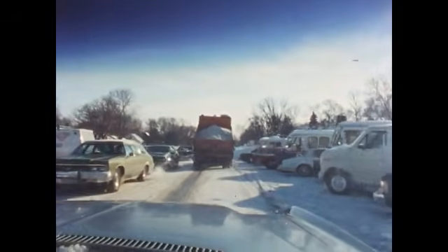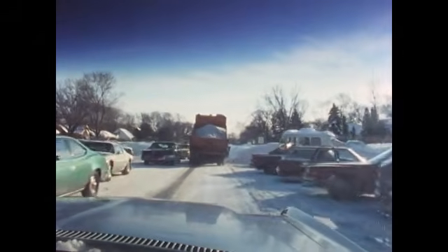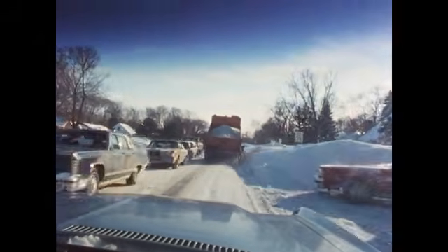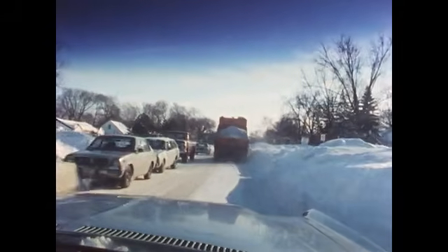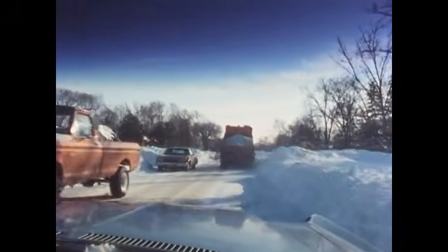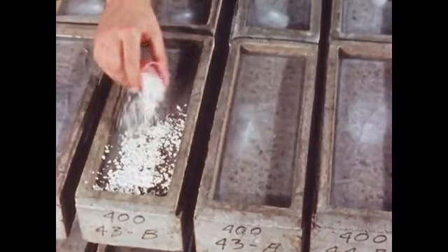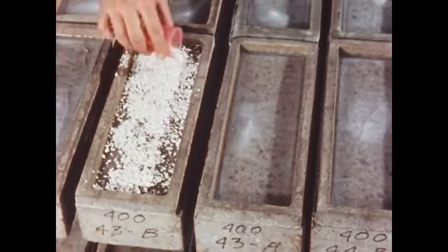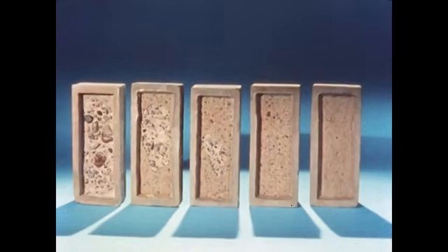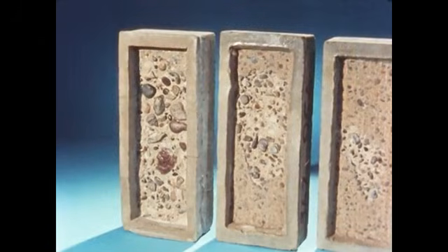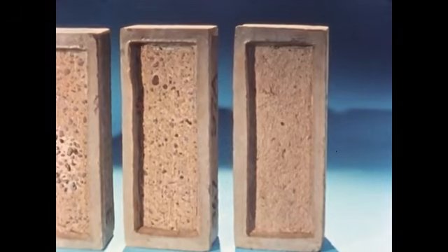Concrete pavements face some of the most severe exposure conditions: cycles of freezing and thawing, wetting and drying, plus the corrosive effects of heavy applications of de-icer chemicals. Each of these laboratory specimens, simulating pavement slabs, has been through 200 freeze-thaw cycles using de-icers mixed with water impounded on the top. The specimen at the left has no entrained air. The air content increases from left to right.